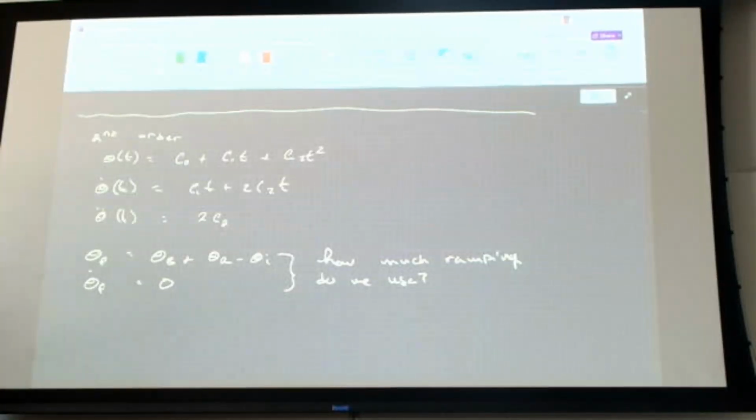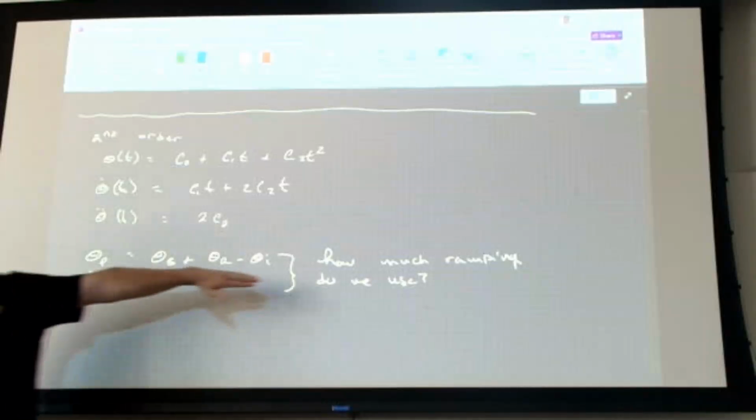Essentially the acceleration or the force or the torque requirements, right? All of them go hand in hand. Force is proportional to torque is proportional to current, right? One's got a moment arm, the other one happens to have the coefficient of KT, some coefficient which relates the magnetic field or the magnetic flux of the motor, right? That's what sets the torque of that motor. It's I cross B. What's B? Magnetic field. Well, what is it for that motor? That's what sets how much ramping you use.